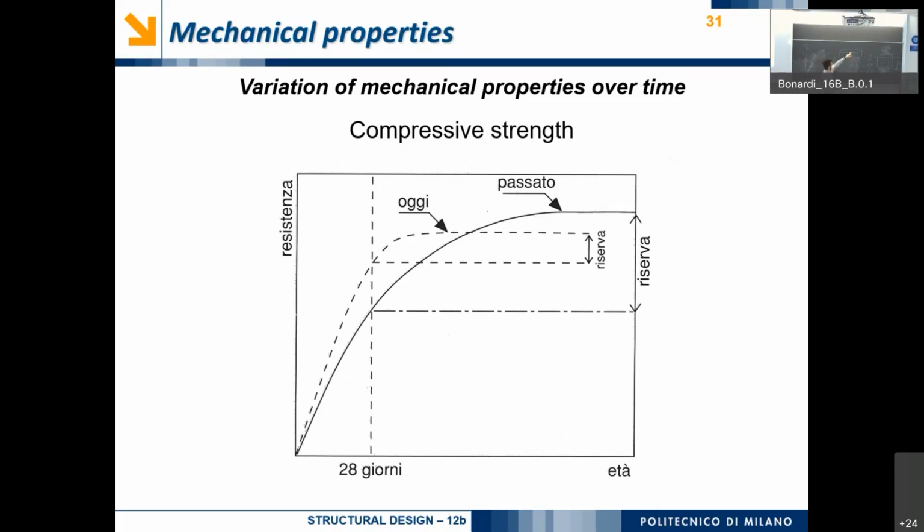Obviously, this process of maturation of the concrete takes time, because initially it is fluid, then it solidifies, and then it becomes stiffer and stiffer. So the more we wait before putting the load on the structure, the stiffer the structure will become in the future.